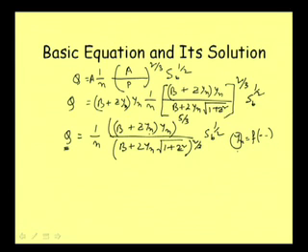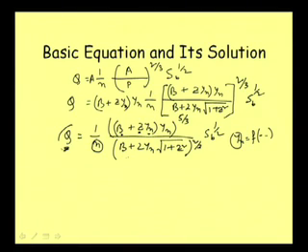But of course, suppose for a channel you know the normal depth, say y n is known, side slope z is known, bed width B is known, everything is known. And of course, Manning's n from the characteristics of the channel is also supposed to be known. Then you do not have any problem in finding the Q. If someone asks you what is the discharge, you can directly put the y n value and calculate the discharge.